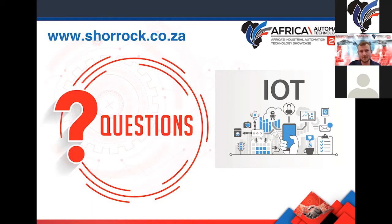Great. What are the different methods of supplying internet to your devices? Okay, so that would be depending on what your customer requires. We have the option to bring in plant internet. So that would be a physical Ethernet line from the customer side. So that's option 1. Option 2 would be Wi-Fi. So if they have a Wi-Fi hotspot available, then you could connect to that via Wi-Fi, making use of a Wi-Fi card. And then we have the 3G and the 4G options.